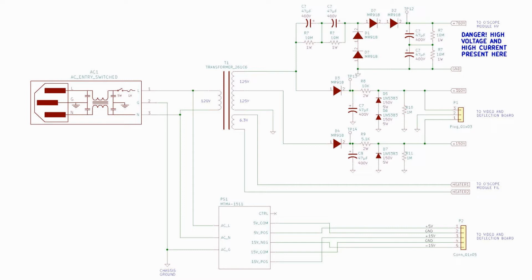The circuit works very well because with the two 47s in series like that, we have 23 microfarads of filter capacitor at nearly 800 volts. This power supply puts out 760 volts with a half a volt of ripple.